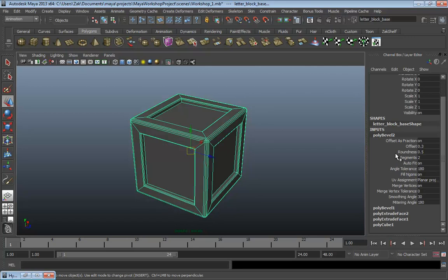Anybody? Want to just fancy a guess? It will bog down. Maya can crash. That's right. You can eventually run out of memory if you have too much construction history going on in your scene. And you have to be selective. Some operations that you'll perform when you get deeper into using Maya, such as skinning a character, are history dependent, and you can't get rid of those as much as you might like to.